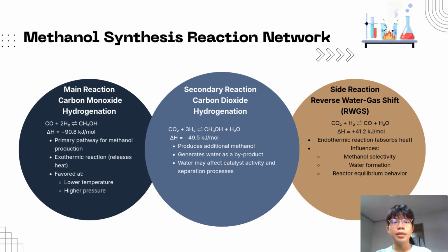In addition, there is a side reaction known as the reverse water gas shift reaction, or RWGS, which converts carbon dioxide into carbon monoxide and water. This reaction is endothermic and can influence methanol selectivity and overall reactor equilibrium.